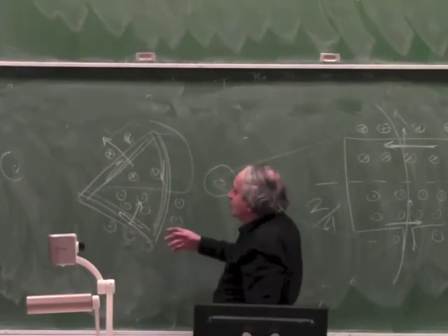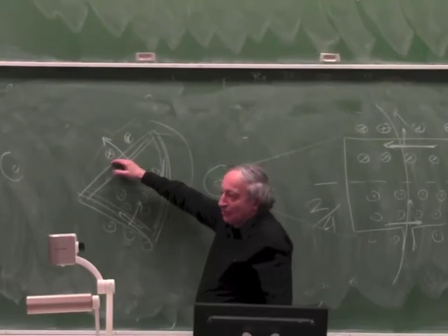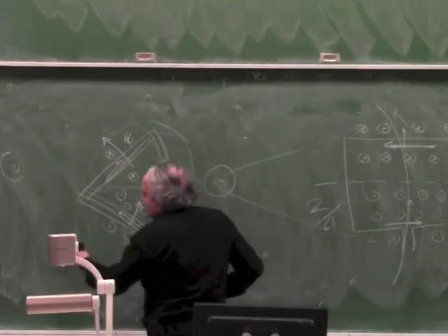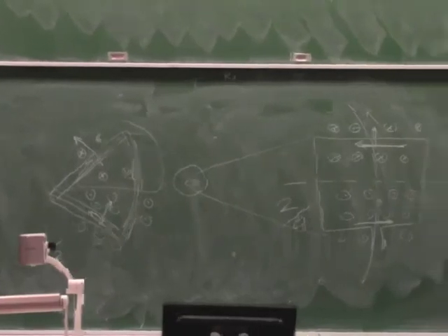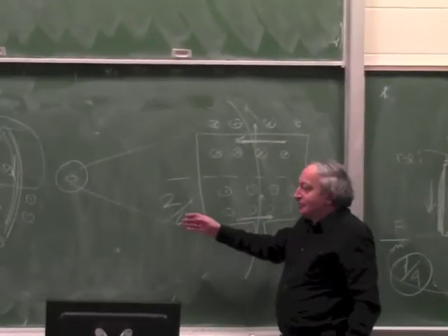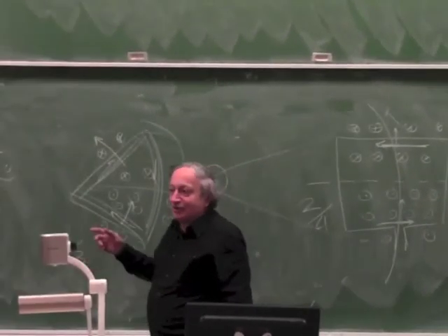So now we reached 2 out of 3. 2 of the arms produce torque or force, and the total weight is 3. So we reached a ratio of 2 out of 3. So we went from 1/4 to 2/4, but because it's rotary, we could get to 2 out of 3, which is a bit better than 2 out of 4.